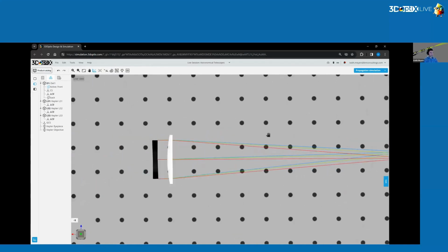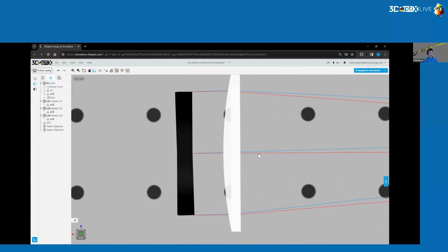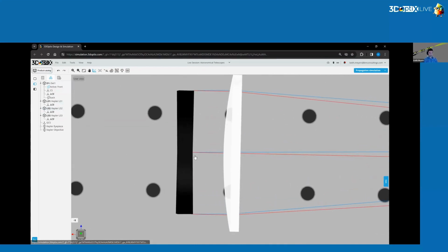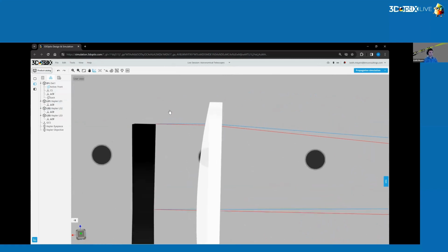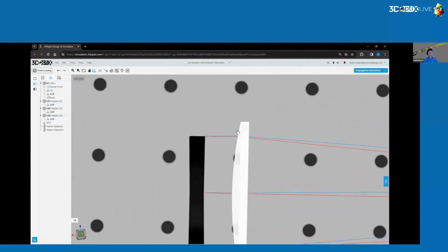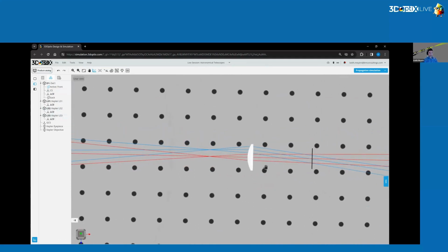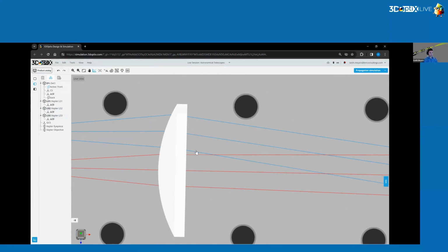Now, to make that a little bit more clear, let's go ahead and turn off the second source at the 1 degree field angle. And our on-axis source here, Kepler source 1, is going straight through the system. So this is a good reference along the optical axis to look at the angles. Obviously we know the input angle here is 1.5 degrees because we specified that for our third light source. And then our exit angle out of the eyepiece is clearly much more than 1.5 degrees.